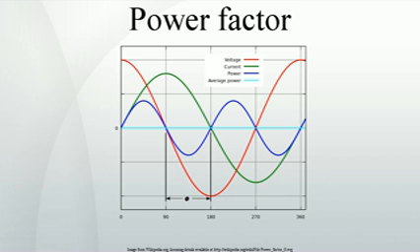Distortion in three-phase networks. In practice, the local effects of distortion current on devices in a three-phase distribution network rely on the magnitude of certain order harmonics rather than the total harmonic distortion. For example, the triplen, or zero sequence, harmonics, third, ninth, 15th, etc. have the property of being in phase when compared line to line.